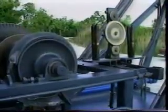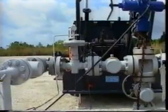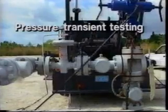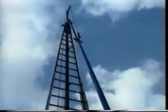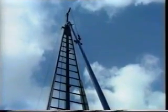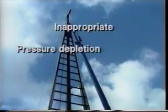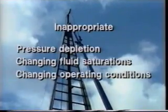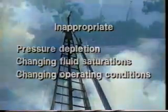All acid treatments require proper justification. This should be based on evaluation techniques such as pressure transient testing or anomalous well performance. Such studies can also preclude the inappropriate and even harmful use of acid on wells that show reduced production due to pressure depletion, changing fluid saturations, or changing surface or downhole operating conditions.